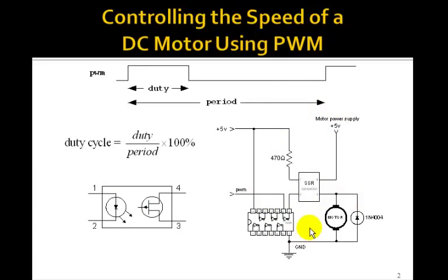This circuit shows how you might set one up. This 5 volts here, on your FPGA board this would typically be 3.2 volts, comes down through the solid-state relay, down through this phototransistor. So you want this to be ground. The PWM signal you can bring in here.